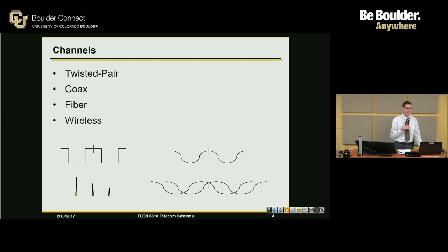Probably the biggest challenge that the telephone network has is that it's used twisted pair for years, because that came along before coax, and to switch from twisted pair to coax would just be a challenge for them because of all the effort to remove all the twisted pair and replace it. So basically, if I come up with a new modulation technique that doubles my throughput on twisted pair, and then I put it on coax, it's going to do even better on coax.